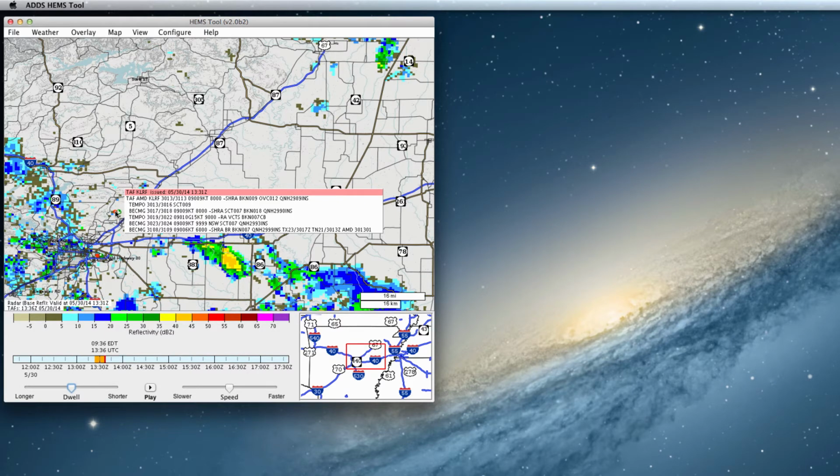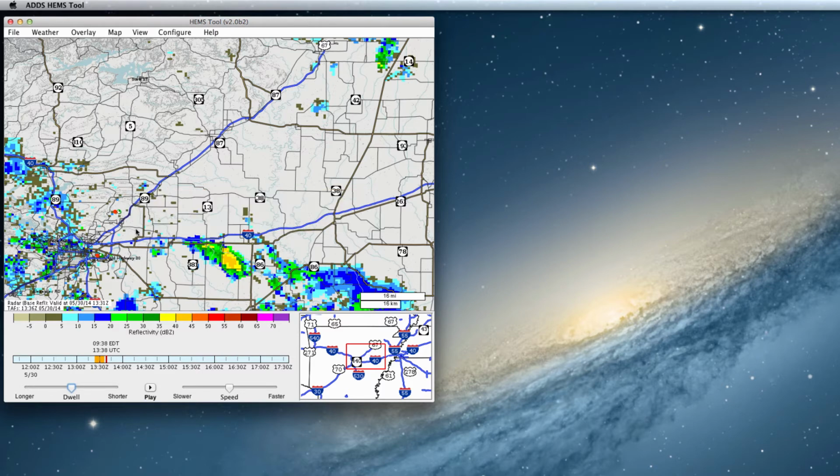You can see that the radar on the map is updating as I speak. Because the selected time is 1330Z, this TAF is represented with 2 symbols, a red symbol for the prevailing condition and a green partially filled circle for the temporary condition. If we select 17Z, we should see the symbols change to show the prevailing condition and the becoming condition, as we do here. If we animate the map, we'll see the TAF change through the whole time series.